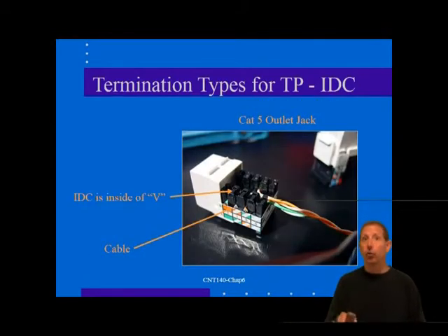However, if the block is incorporated into the connector module, the combination can be certified to Cat 5e, and the 110 strip has the advantage that it can be terminated with conventional punch-down tools, and its connectivity and longevity parameters are well established. On the other hand, the strip is often wider than the connector module that it is attached to, which limits placement of a mounting plate.